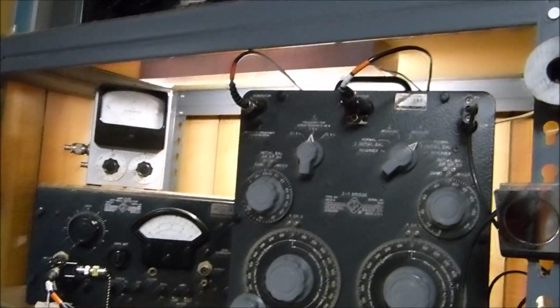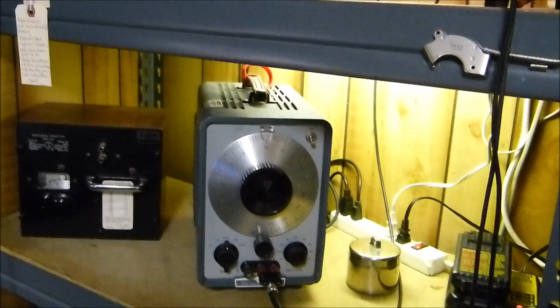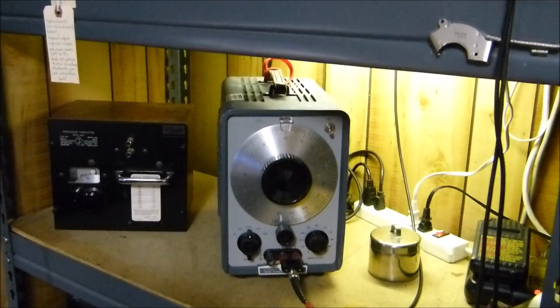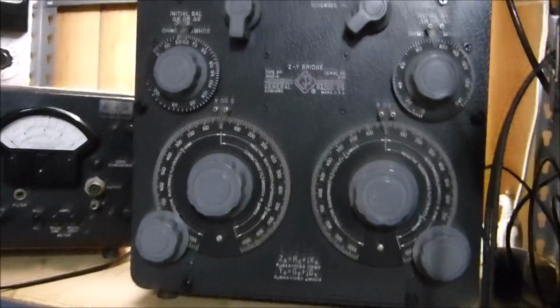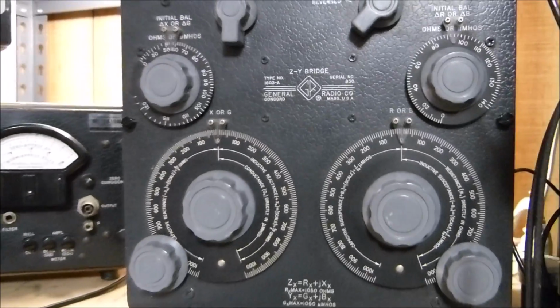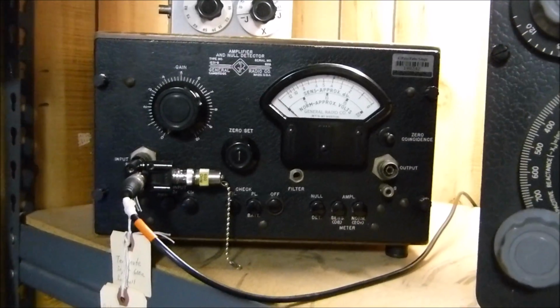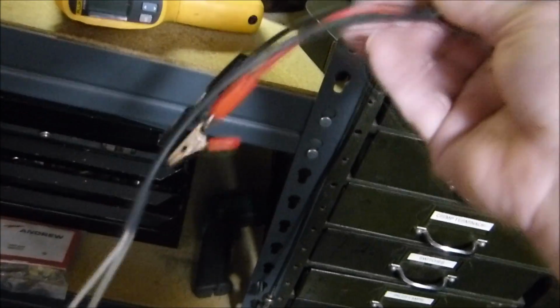Right down here is my impedance measuring section of my shop. I use this old HP signal generator. I love GR equipment. This is a ZY bridge, as you can see. It measures impedance and admittance. This is the dip meter I use for it. I just turn it on, and then I have the wires hanging here somewhere. I think it's these right here, or some of them, wherever I can clip across the inductor and I can start measuring impedances. They're just long enough to reach over here to my workbench.